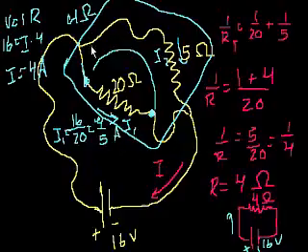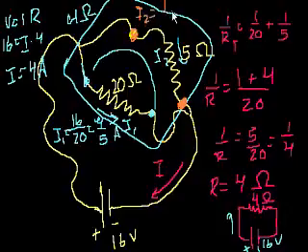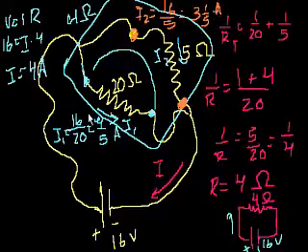And similarly, what is the amount of current flowing through here? I2. Let me do this in a different color. It's getting confusing. I'll do it in the vibrant yellow. So for the current flowing through here, once again, the potential difference from here to here is also 16 volts, right? So I2 is going to be equal to 16 over 5, which is equal to 3 1/5 amps. So most of the current is actually flowing through this, and that makes sense because the resistance is less, right? So that should hopefully give you a little bit of intuition of what's going on. And less current is flowing through here.